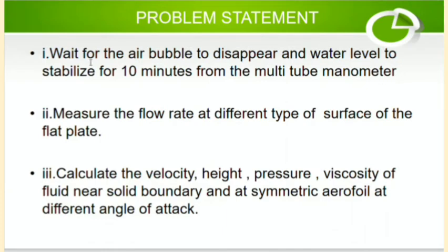For the problem statement, we first need to wait for the air bubbles to disappear and the water level to stabilize for 10 minutes in the multi-tube manometer. Second, measure the flow rate at different types of surface of the flat plate. And last, calculate the velocity, pressure, and viscosity of the fluid near the solid boundary and at a symmetric aerofoil at different angles of attack.